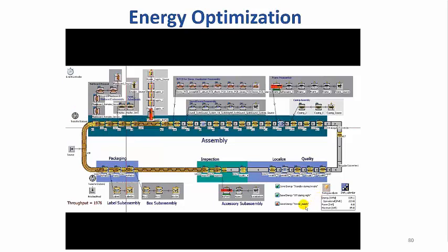In our model, the Save Energy Power Supply checkbox sets the power supply line up so that the buffer is filled at the start of the simulation, and thereafter it's fed only after 50 units are left in the buffer. Now, after running our model for one day, our Energy Analyzer's display panel shows that we've decreased total power consumption from 819.1 kilowatt hours to 755.9 kilowatt hours. And once again, we achieve these savings without any decrease in throughput.